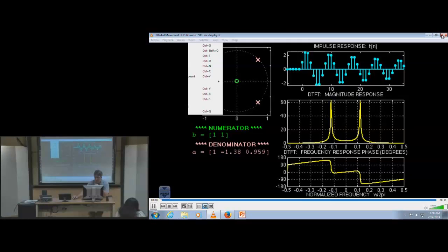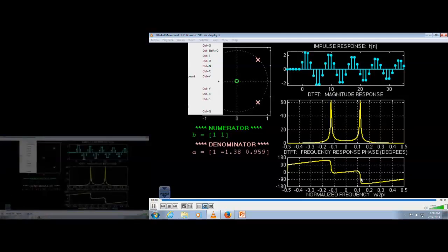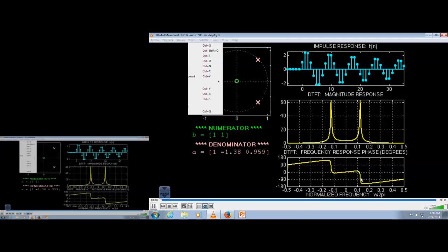One other thing, you'll see the phase, oddly enough, even though IIR filters don't have linear phase over all frequencies, over the pass bands you actually see near linear phase. So what's interesting about certain IIR filters is that over the frequencies you care about, the response of the filter is nearly linear. It's almost linear, but it's not linear phase, obviously, over all frequencies.